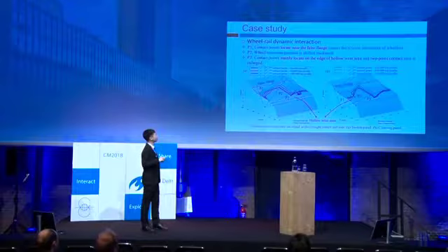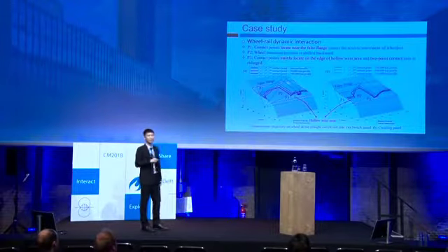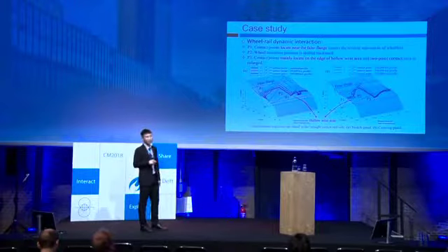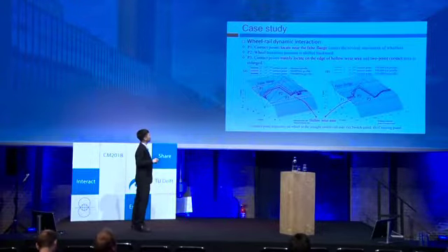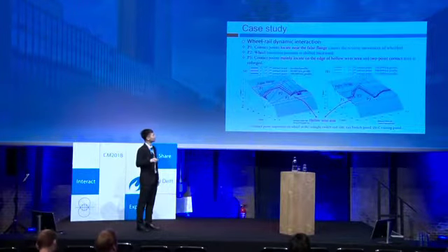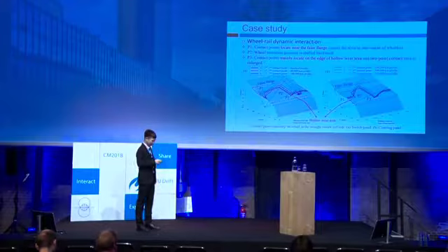For part 2, it is observed that the wheel transition position is shifted backward. This is the reason why the position is shifted backward to the stronger cross-section of the turnout rail. This is the reason why the vertical wheel-rail force decreases. And for part 3, the contact point is mainly located on the edge of the hollow wheel, and the multi-point contact area is enlarged.